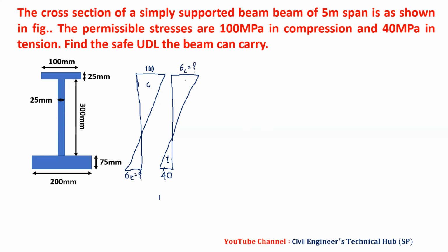Now we have to check, by using this, what will be my moment of resistance? And the minimum of the two will be considered as the moment of resistance. Keep in mind, not the maximum, the minimum of MR due to compression and MR due to tension. So now we first have to find I. We will go with y bar equal to summation A y bar upon summation A. You have to write the formula in the examination, it is most important.